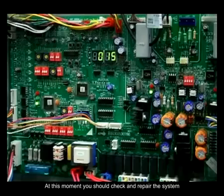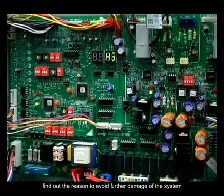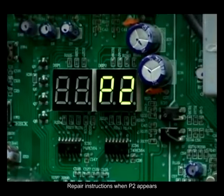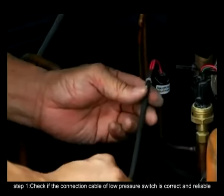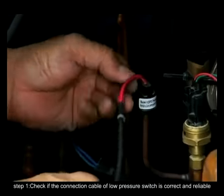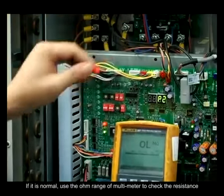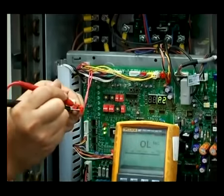At this moment, you should check and repair the system. Find out the reason to avoid further damage to the system. Repair instructions when P2 appears. Step 1. Check if the connection cable of the low pressure switch is correct and reliable. If it is normal, use the ohm range of a multimeter to check the resistance.